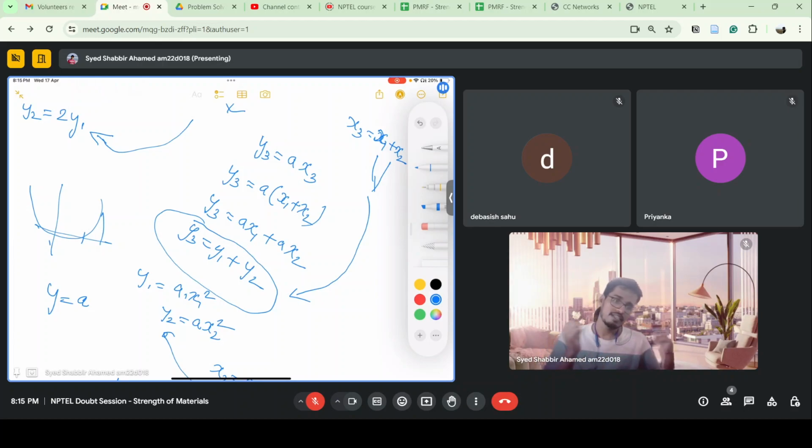I can have axial, torsion, bending, everything. Combined stresses might happen. There is also thermal expansion, due to which thermal stresses might happen. Everything will come together, and because we are assuming that everything is in the linear zone, we can take the individual effects from each of them and sum them up and get the resultant principal stresses.